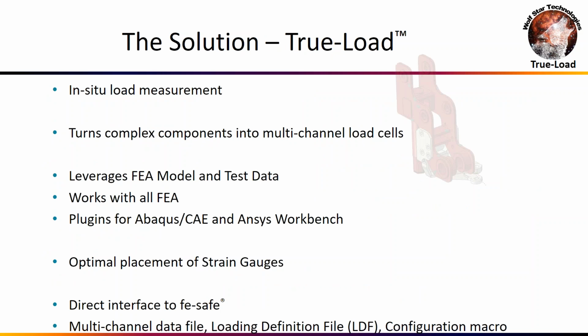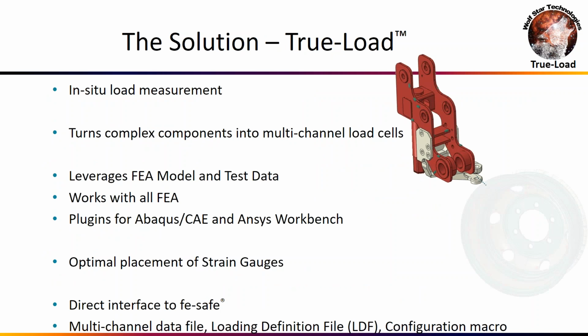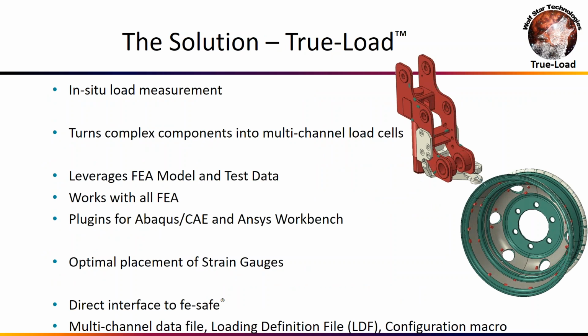So the solution here, quite simply, is TrueLoad. So TrueLoad does, in 3 words, what's called in situ load measurement. So in situ means in location load measurement. So we're going to turn your components into a load transducer, and we're going to do that by extracting a correlation matrix from the FEA model. And this works with all FEA codes.